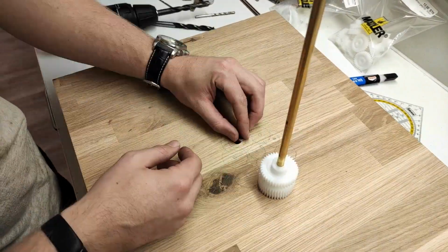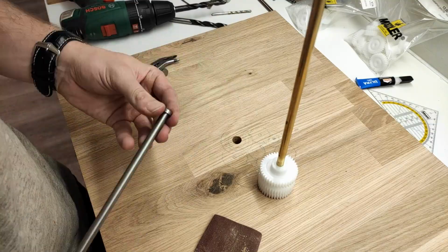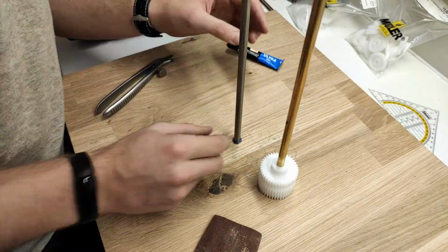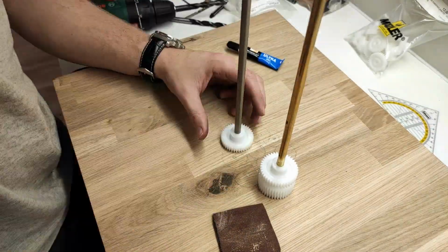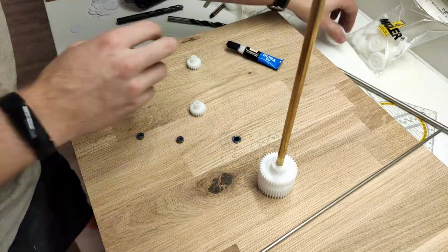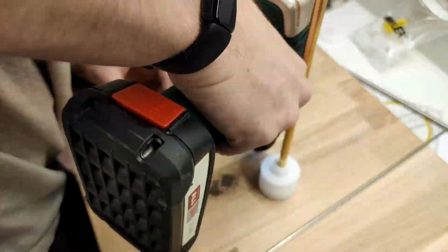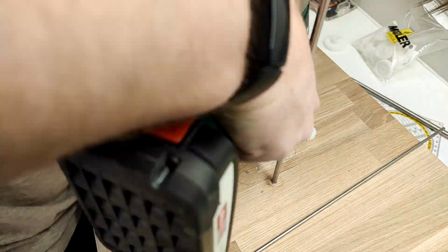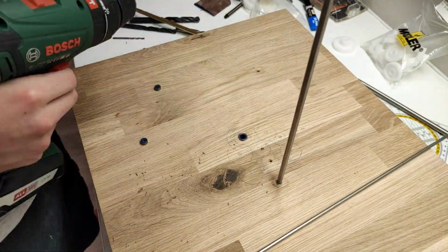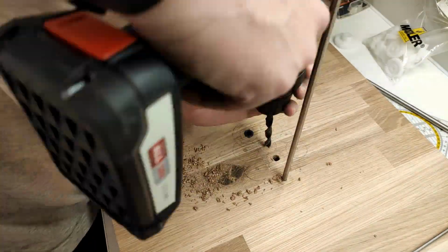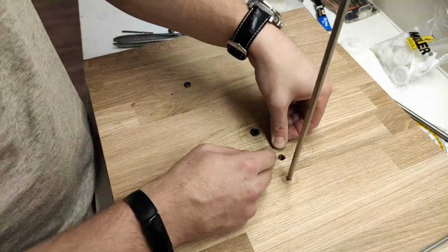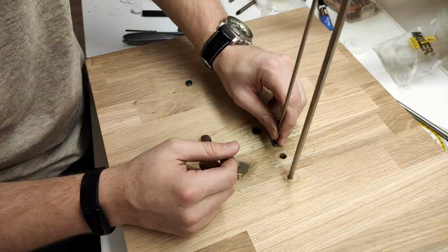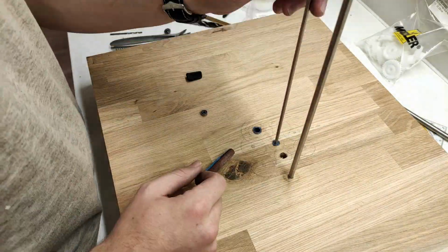In order to create the whole gear system, you can see me here drilling some holes for some ball bearings, which will then hold the axles to which the gears will be attached. And here you can see me fitting the first ball bearing with the steel axis into the hole that I drilled, just using some super glue. I actually wouldn't recommend using super glue to glue metal to wood. I would rather use 2-component glue, which I realized later when some of these ball bearings were coming off again.